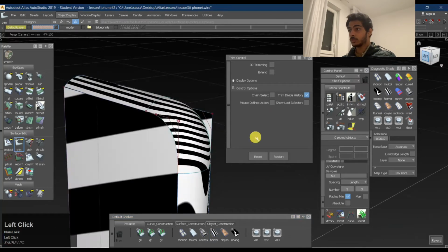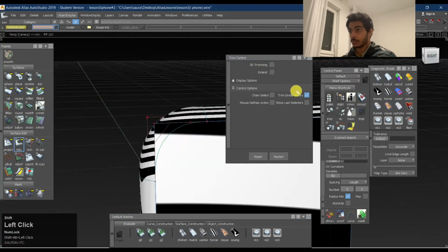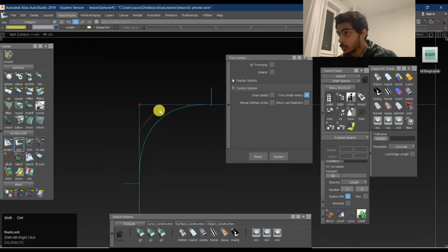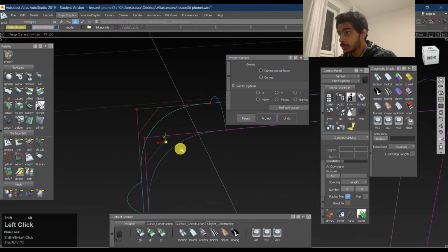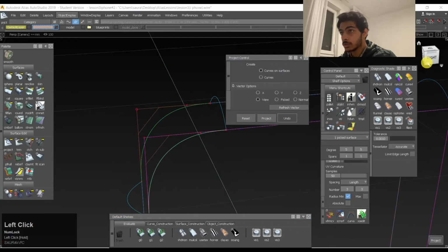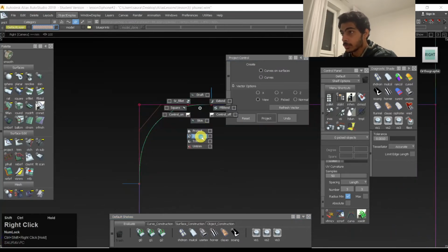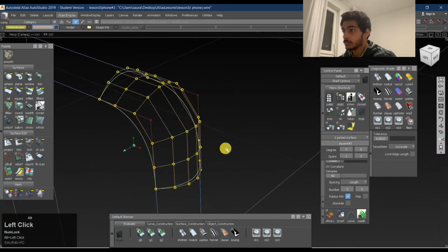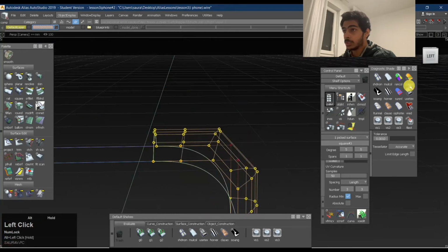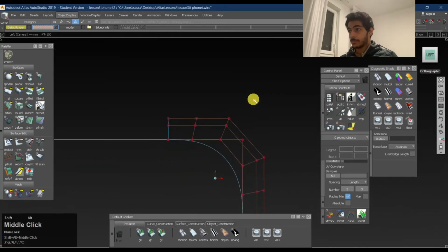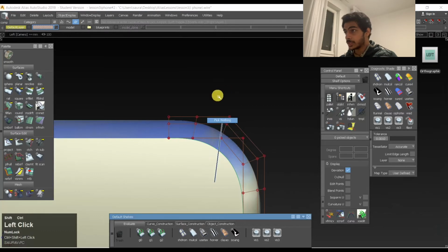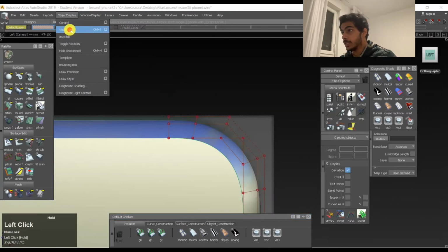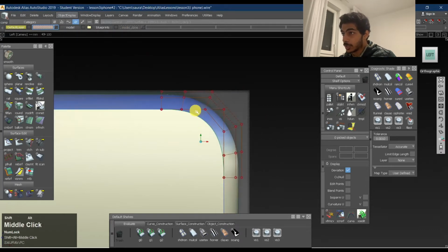Now the same thing goes with this as well. Over here, we need to project again and trim again. We'll use the surface edge over here and trim. So we have these points over here. Now what happens is, if you see, if I switch on the blueprints, if I go on to object display and visible, it will be visible for us.